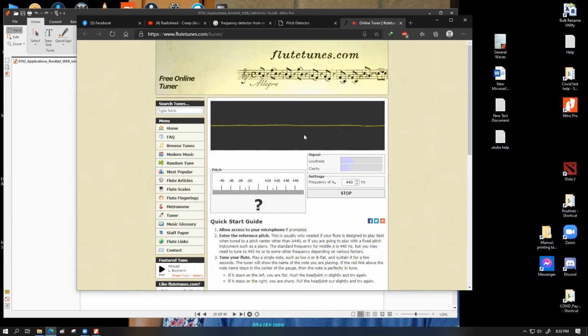The reason I'm telling you this is that if we want to use a solenoid-based microphone, then we have to make that vibrating part of the microphone extremely light so that it could vibrate at any of the frequencies that we shoot at it. That would require the microphone to be made very light and very, very subtly attached in the magnetic field. And designing a physical object in that manner, which should also last long, is actually quite difficult.